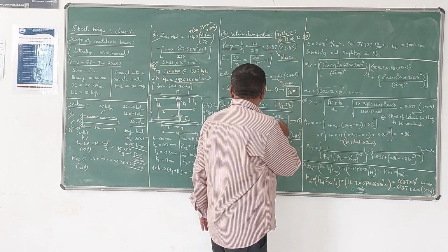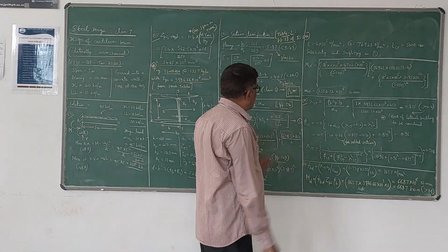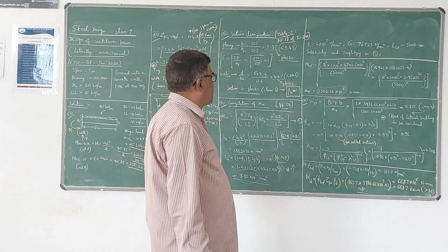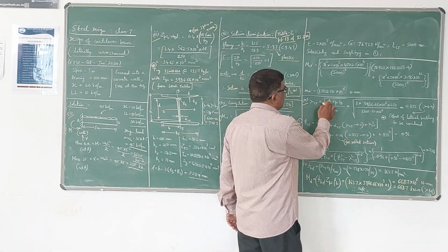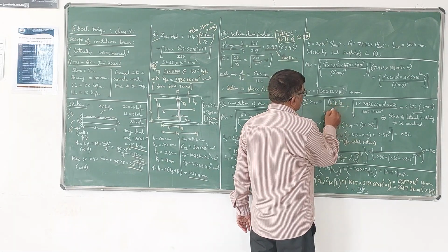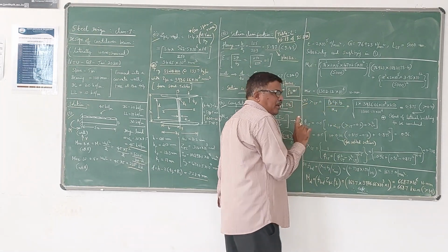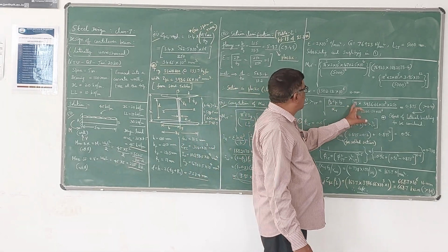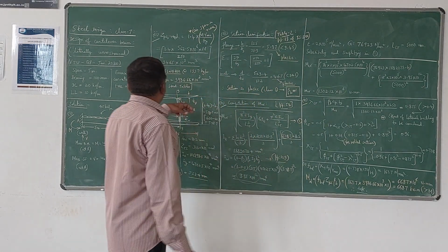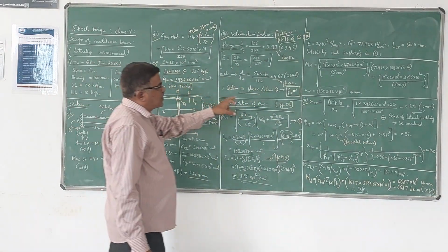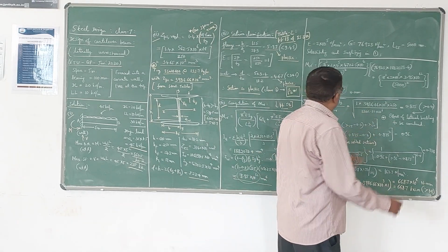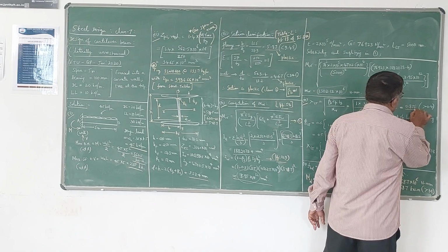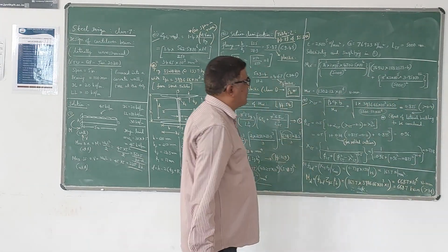Then using the same page, page 54, you have to calculate certain parameters, the non-dimensional slenderness ratio lambda LT, which is given by the root of beta b Zp into fy by Mcr. Everything should be in Newton and millimeters. Please note that beta b is 1 because it's a plastic section, into Z is whatever you have provided, 3986.6 into 10 power 3, into fy is 250, divided by whatever Mcr you have got. You substitute, and you will get a value, lambda LT.